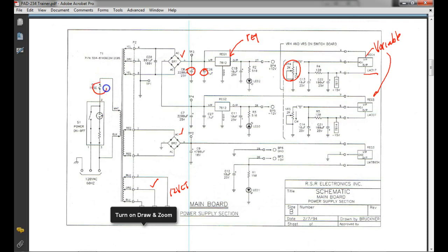Of course, this is our fuse. This is a neon bulb, the symbol for a neon bulb. And how does a neon bulb create light? This is really neon. We call them neon bulbs, but the only ones that glow orange are neon. The ones that glow blue are not neon. The ones that glow green are not neon. It's another gas, but we still call them neon bulbs. So most gases, if you shoot electrons through them, they glow. And that's what we're doing here. So these guys here will glow orange. Anytime you see that little symbol with the dot up to it, that means this is a neon bulb.